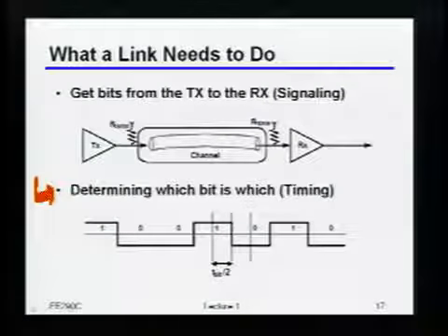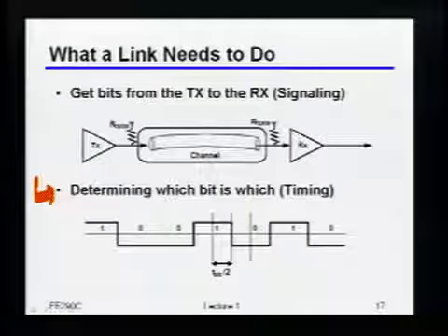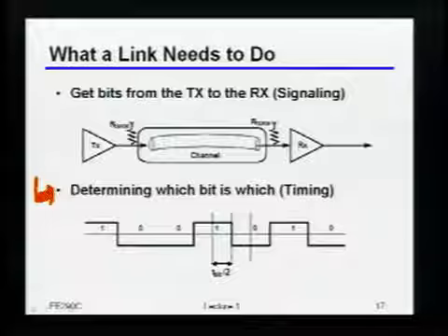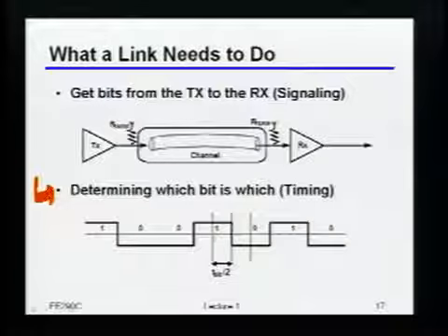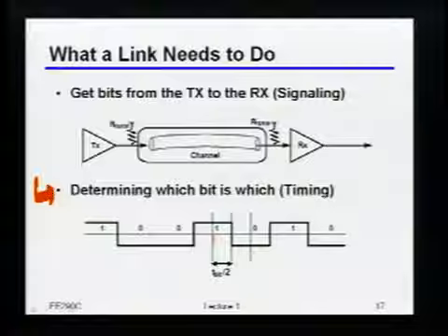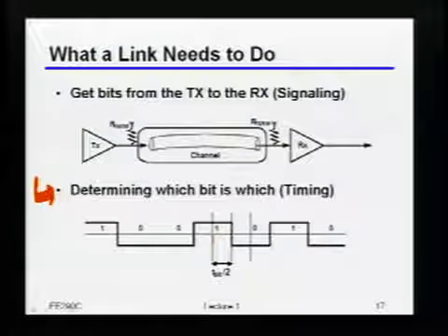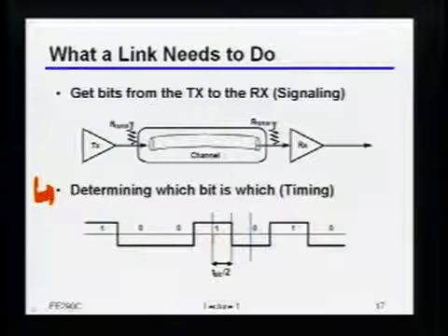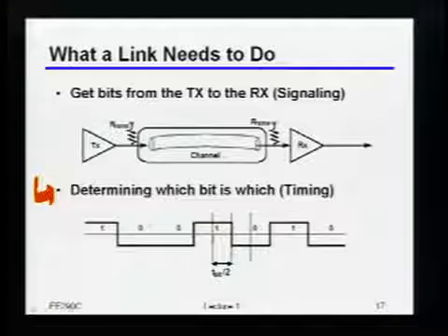Okay? Because like I said, if I'm talking from a chip in Arkansas to Wisconsin, they don't know squat about which clock is which or which bit is which. So you somehow have to figure out when I should actually look at the voltage that's been sent to me and decide whether that bit was a 1 or a 0, or in fact, I could even do more complicated things like sending multiple levels of information.